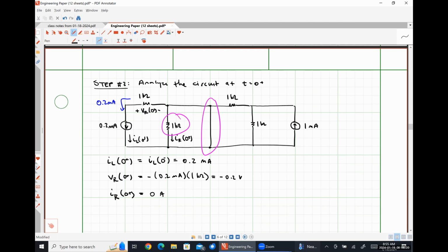There would have to be no current flowing through the inductor at 0 plus, which means we would put in a 0 amp current source, which is a fancy way of saying an open circuit. So under that specific condition, we'll put an open circuit because it's just forcing there to be no current flowing, still maintaining the prior condition. It's just depicted slightly differently.